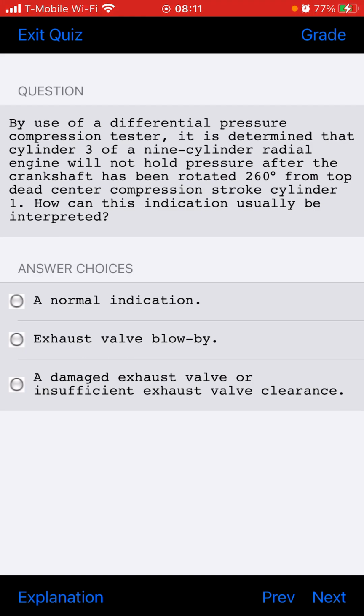What procedure should be followed when valve blow-by is indicated by a hissing sound on the reciprocating engine when pulling the propeller through? Perform a cylinder compression test to identify faulty cylinders.